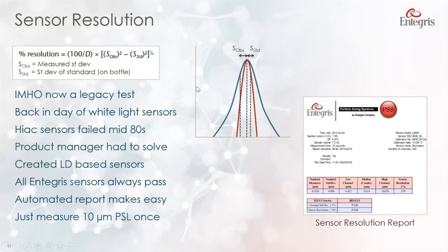Then when we do a measurement, no sensor is perfect. So you somewhat broaden that distribution due to imperfections in the sensor. And there's a calculation you see here where we need to have this value below 10%. All we do is when we measure the 10 micron standard to perform the calibration check, we now have a report we can run where it will automatically calculate the sensor resolution test.